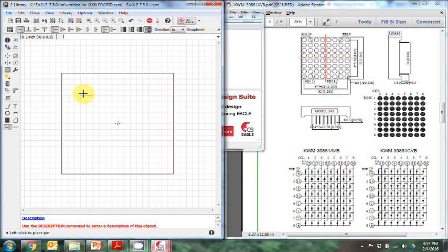Now the pin tool allows us to place pins down in the diagram, and the little green circle is where wires will be connected to things on the outside. And I want to match the numbering of the pins on the diagram here. So this is not how they're physically wired, but this is how they're wired on the schematic, and it's going to make a lot more sense.